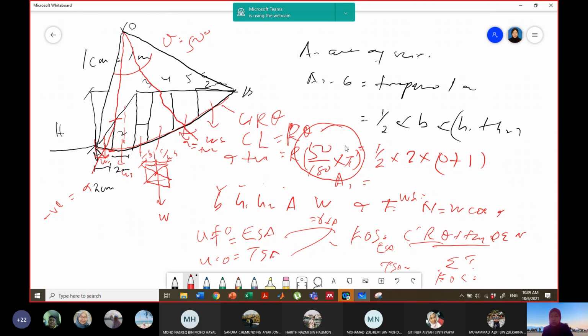This is wrong, totally wrong, because the factor of safety is mostly designated at a maximum of around 2.5. If you look at the previous introductions to slope stability, I mentioned the guideline on how to check whether your calculated FOS is correct or not. So if you have a building, the recommended FOS is 2.5. If you get an FOS of 100 something, or 200, or 150, there is a mistake in your calculations. It is an illogical answer to have.